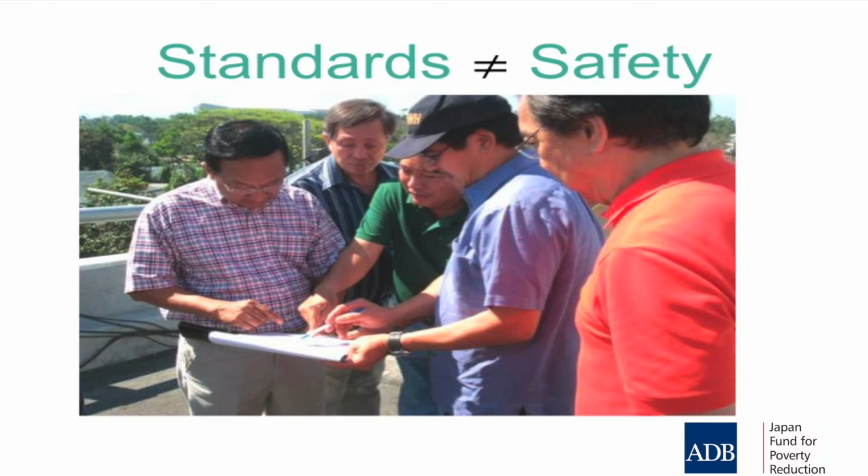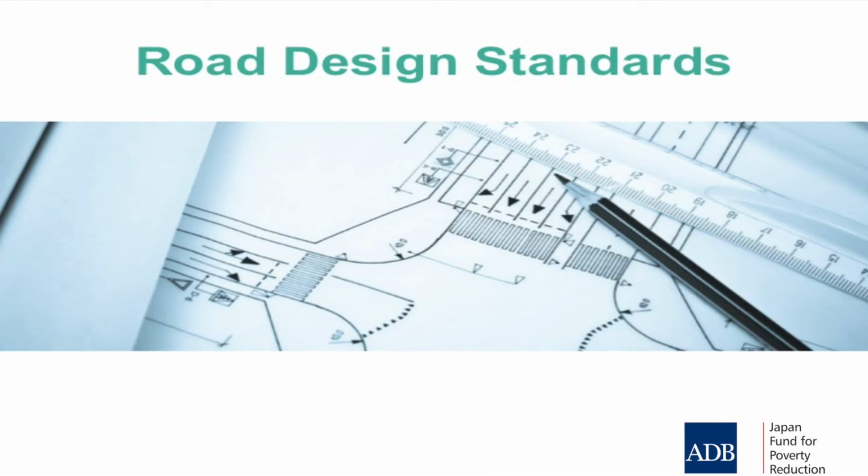Do they take into account the road users? You can also have a look at your road design standards, and if you have a big population of motorcycle riders in your fleet, maybe look at developing specific standards for motorcyclists. There are some out there, but there is a lot of work still to be done worldwide in road design and road engineering to improve the safety for motorcyclists.